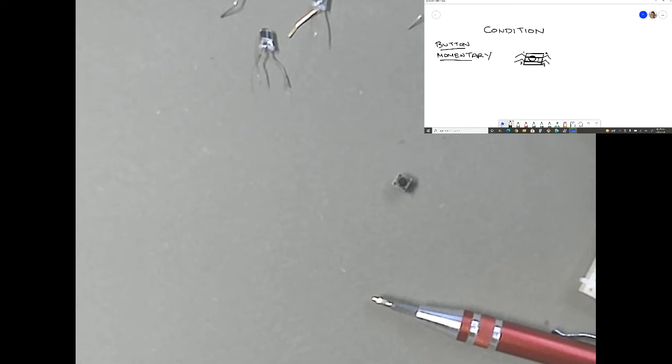All right, so let's try. So here we go. We're going to draw a schematic now. So remember, that's the plan of our circuit. Okay. And this will be our Uno. We're going to use 5V as usual. We're going to use our resistor because we need to resist some of the electricity. And let's go ahead and use 470.